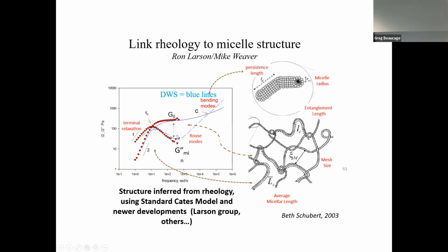So people looked at different kinds of viscometers to overcome this. You want to get to really high frequency because there's a lot of information here for polymers. Like this becomes linear again. You get kind of local flow when you get to really small sizes, and small sizes you see at high frequency, like a small bell is a high frequency bell, high pitch, right? So if you have a network of entangled chains and you want to see the motion within those tubes, you need to go out here, and you can't measure that with a mechanical viscometer. So you need something else.